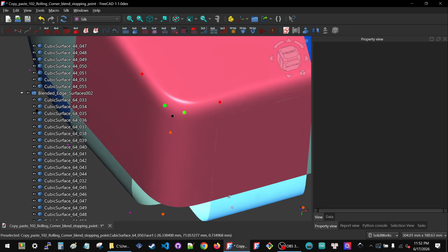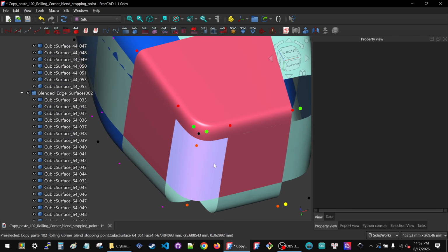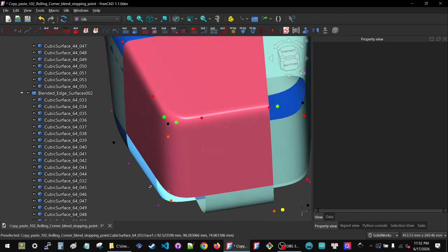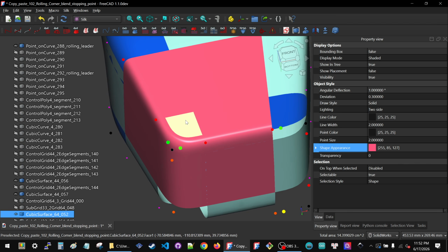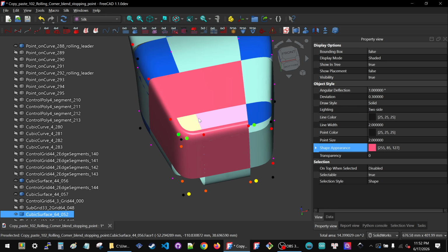This separation of the blending into two zones with different sizes, with a large fillet in one direction and a small fillet in another direction, is what I call a rolling blend. And it relies on this triangular surface. Now, this guy here is not very high quality, but once again, it scales, so I use it until I'm really done with the model.